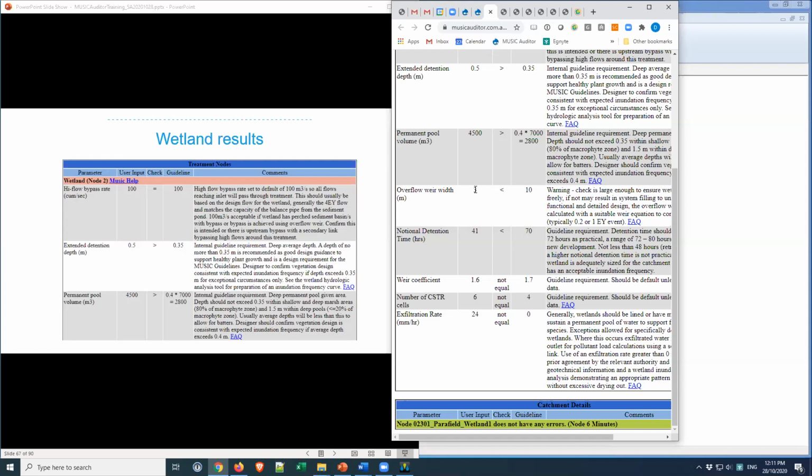So if you're dealing with very large wetlands, it becomes very important that you've set an appropriate weir for that wetland. That doesn't happen too often. Most wetlands, if you've got it left at the 3 metre, it's probably okay. But I'd suggest that if you don't know what it is, it's better to be too big than too small, so just make it 10 metres or something like that. If you do know what it is, then use what's designed and accept that.